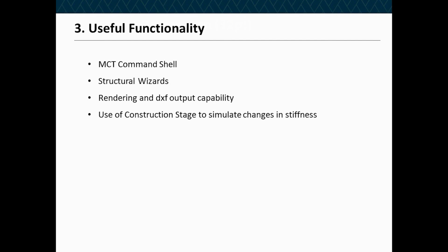The MCT command shell is fabulous as well. We have spreadsheets for precast segmental bridges, for example, where we just have to enter the tendon data from the contract drawings, and it will generate the syntax for the tendon layouts within MIDAS. Simple. And you can do that because of how easy it is to generate the codified syntax that you can then import through the MCT.